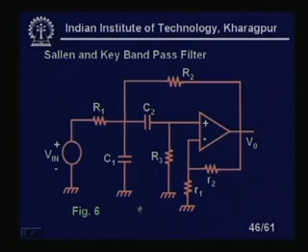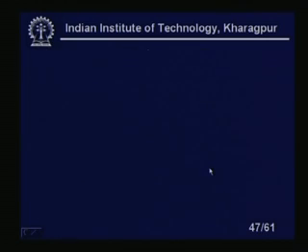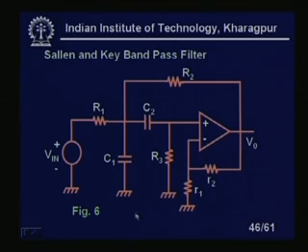So, this is the band pass filter. In the band pass case, we need one more resistor R3, all other resistors are the same as before, but the structure is slightly different, right. It has negative and positive feedbacks. To make the circuit stable, I have to give a certain amount of negative feedback, right. So, this is our band pass case.